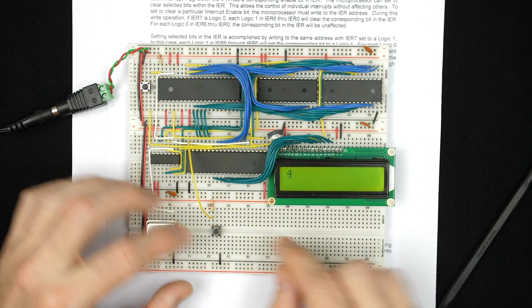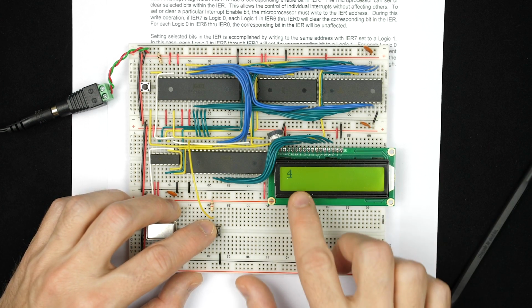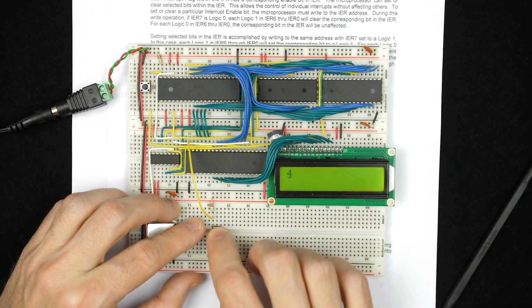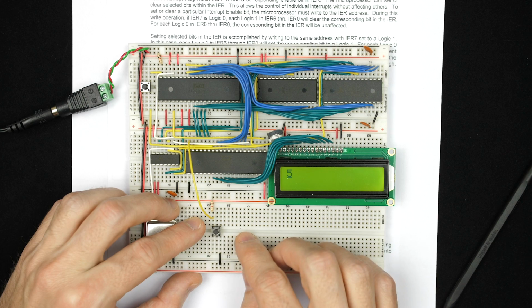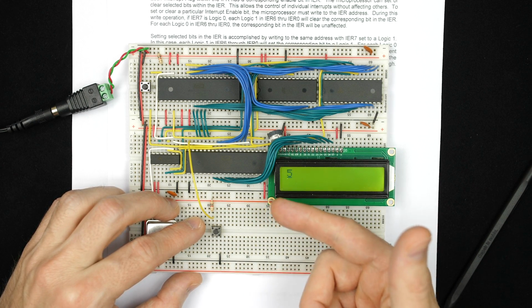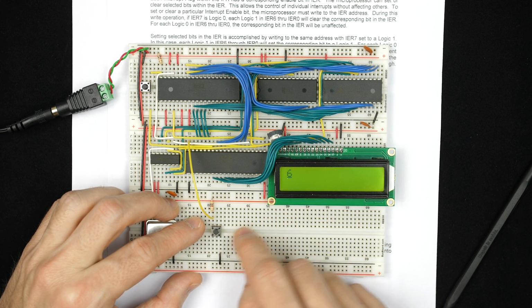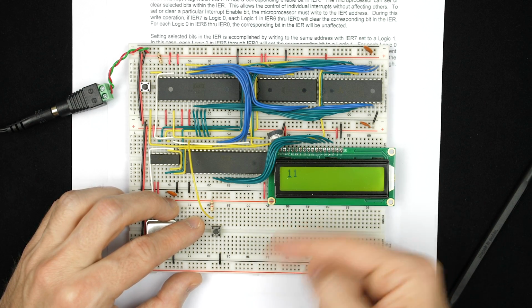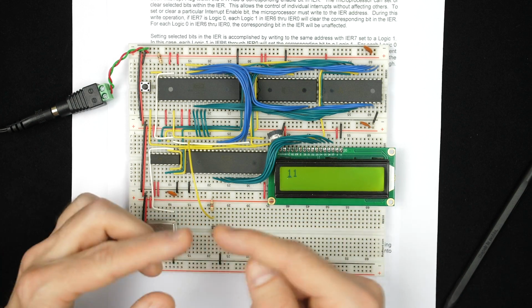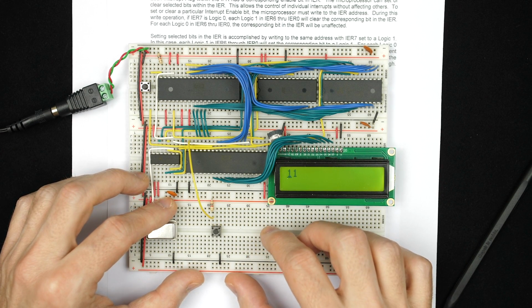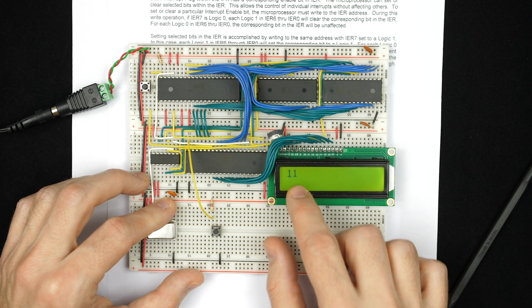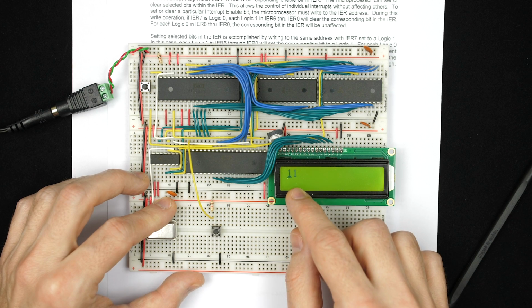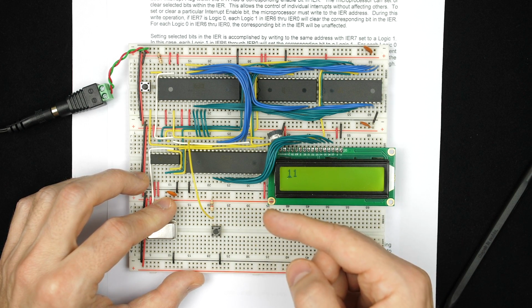And I don't know if you can tell, I can definitely tell it's very slow. It feels kind of laggy almost because it's sitting in that loop in the interrupt handler. So when I push the button, there's a noticeable delay from when I push the button to when it increments, and that's because it's in that loop in that interrupt handler, waiting for any switch bounce or whatever to subside. And the display is not going to update, even though it increments the counter immediately. The display won't update because we're just inside that loop in the interrupt handler.